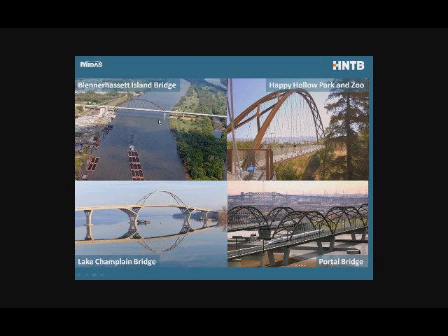So let me just run you through this, starting in the upper left corner. Here's the Blennerhassett Island Bridge. That's an 878-foot span, 100-foot wide. This is Blennerhassett Island. As far as I know, this is the longest span bridge in the world if you stick with the network-tied arch definition. You can see it very nicely. We have the inclined hangers, and each hanger crosses another hanger at least twice. There are longer span bridges in the world where the hangers don't cross. They're still inclined but don't cross, in Norfolk, Rotterdam, for example.